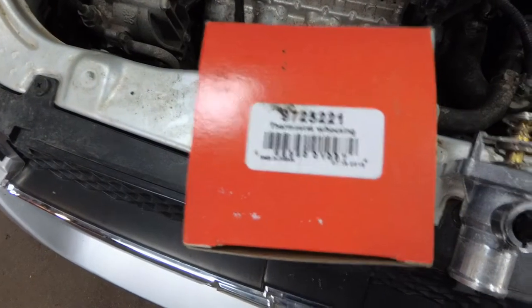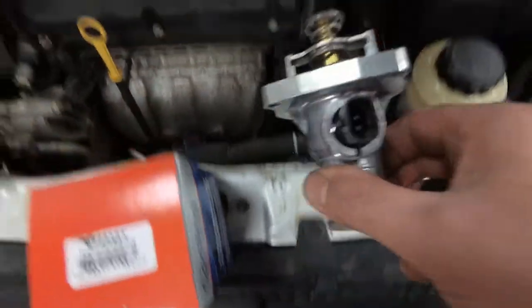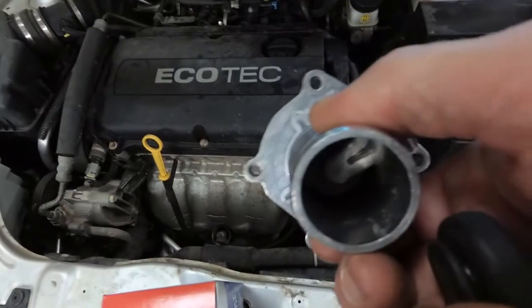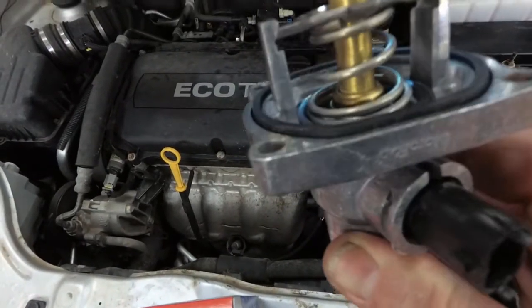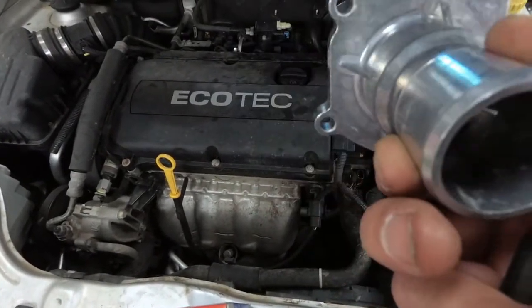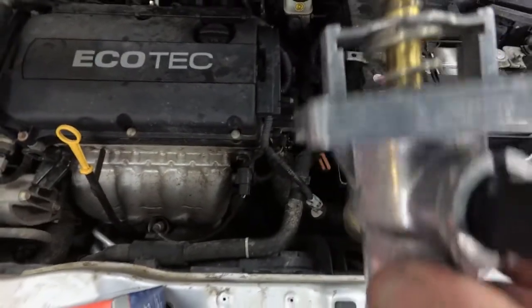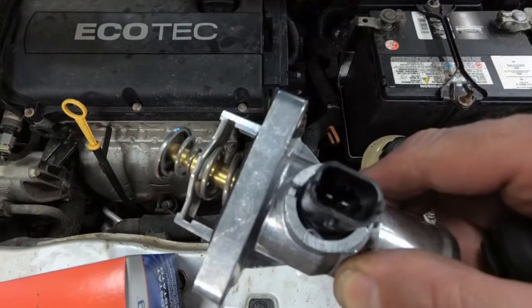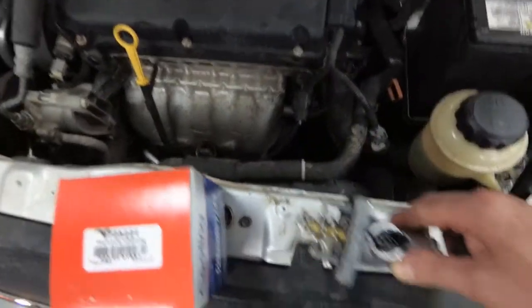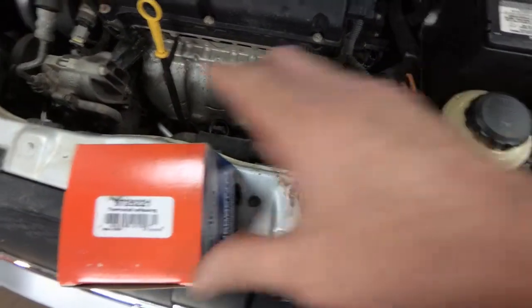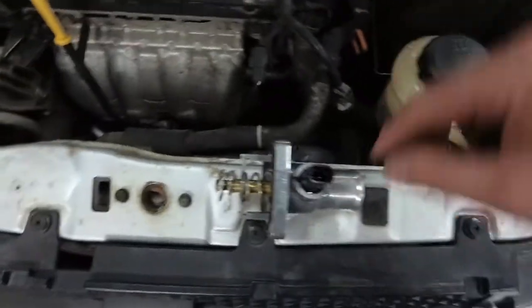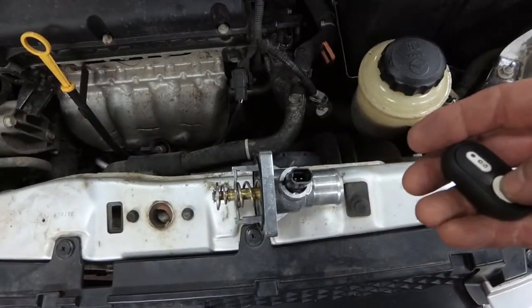So there is the part number for the thermostat assembly. Here it is here. You can see it comes with the heating element inside there and the housing. Looks like there's 4 bolts that hold it on. Looks like it's fairly convenient to replace. But we're going to put an ohmmeter across this and compare it to the original one. Remember, the service information didn't mention anything about checking continuity of that, but we're going to check it.